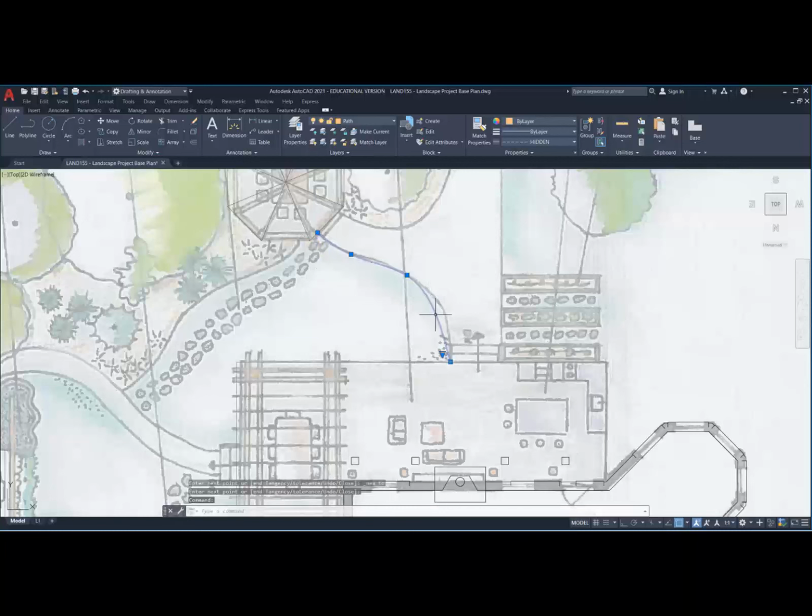And then this curve I can adjust. I can pick these nodes and I can move them. Oops, this one snapped to the end. You've got to be careful of that. I'm going to select the none option here, and I'm going to move that here so it better fits my sketch. That's not too bad. I can add points to it, remove points, stretch points, do whatever I want. So what does add do? Okay, I get another point. Good. Now I can put this one here and this one over here, and it better suits the line work I have. Oops. Anytime you make a mistake, just undo. So there's my curve. That's the one I'm going to live with.